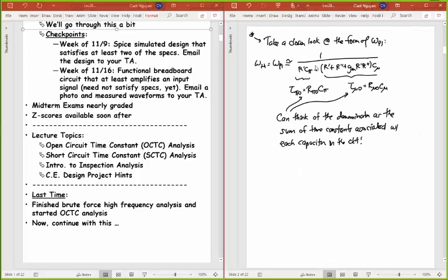And you can see with C mu, I also had an equation for a resistance, but this is more complicated. It includes that R prime and R double prime, but it also includes something that looks almost like a gain term. So it includes the gain of this thing, which is gm times R double prime, if you recall, it was the gain. And we're multiplying that by R prime, which means this is a big resistor right here. And that's going to tell us in the future C mu is going to be an important capacitor, because this is going to be a very big term that will almost dictate what omega H will be.